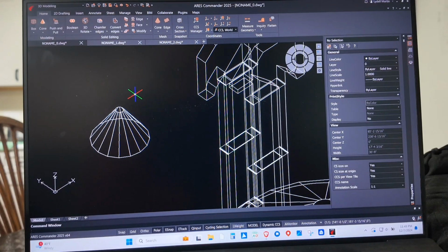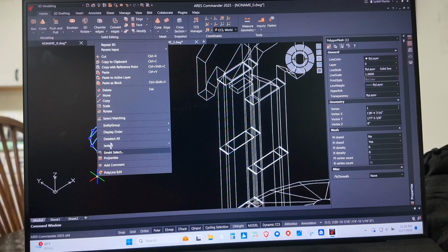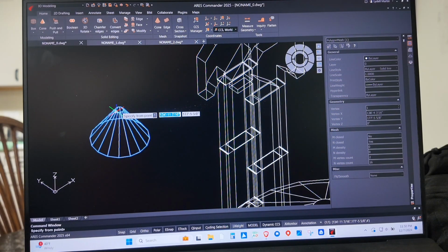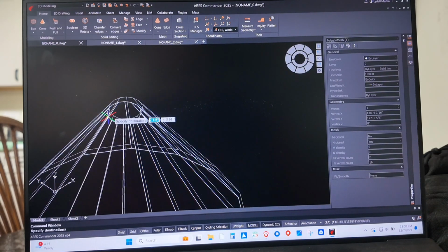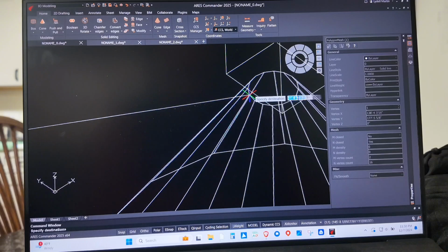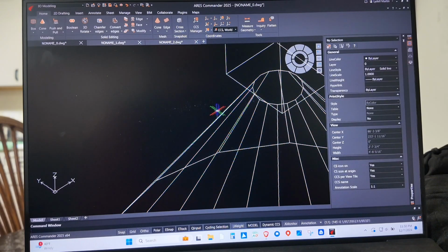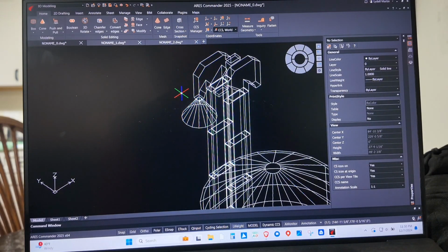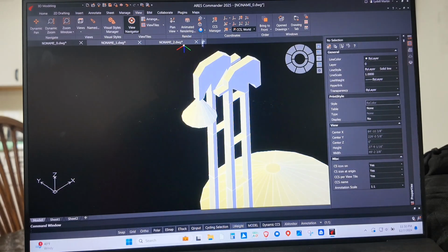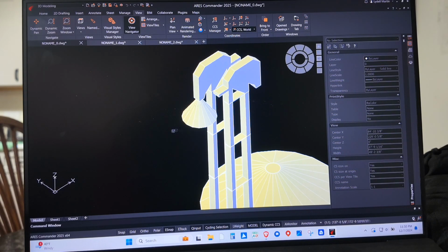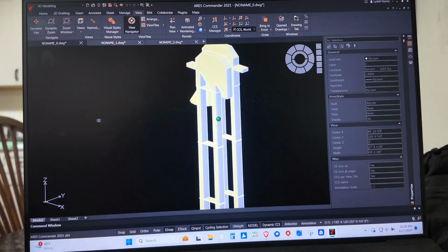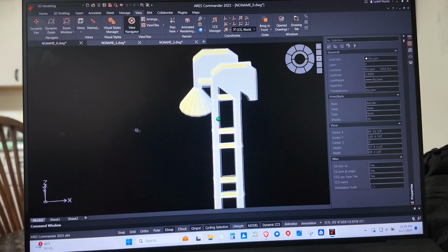That looks good. Now I'm going to select that distributor, right click, hit move, and try to select a spot on the front edge of it, this side, top, and bring it up here and select the center front. Now we have a distributor. If we go back here to view, we hit conceptual, we have a distributor on our elevator. We hit our restrained view here. We can see that we have a distributor.